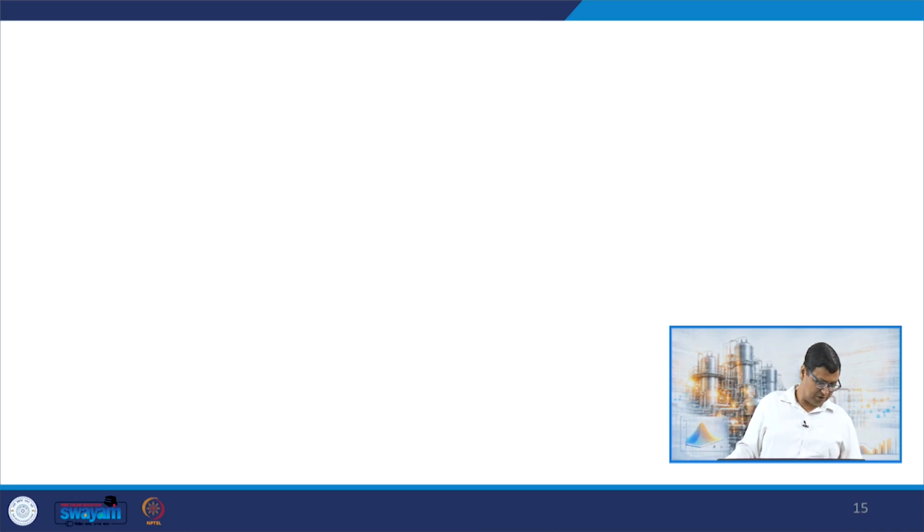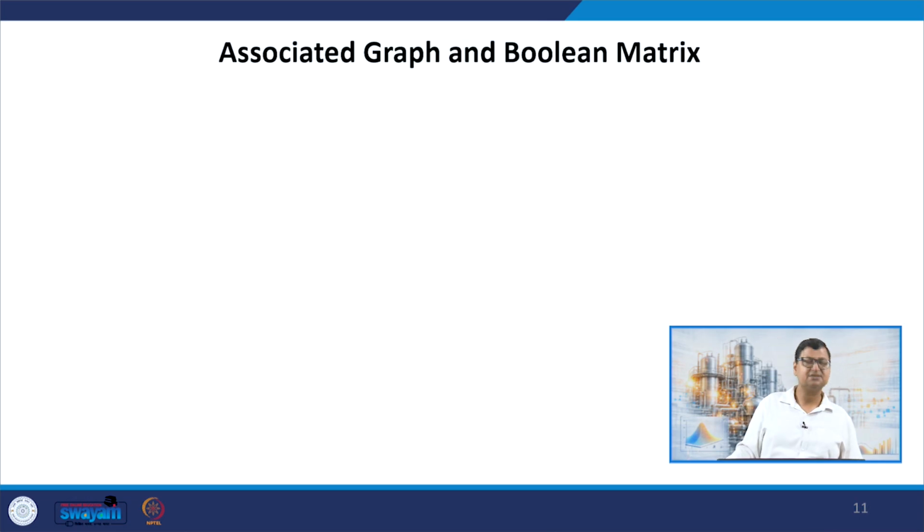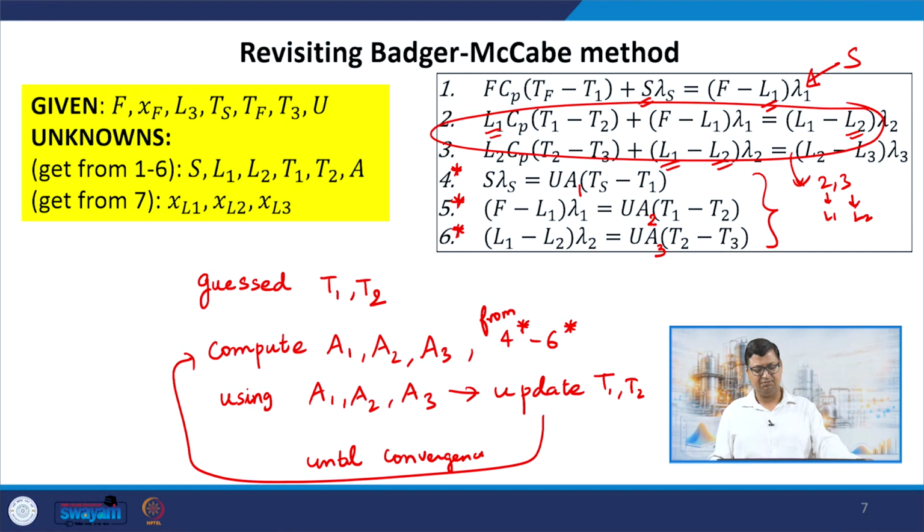Again, for this particular example, we only had a 6 by 6 matrix. So, the benefit from doing this iterative scheme may not be as high, since we could have done a Newton-Raphson for this, and as we have demonstrated, it works quite well. But as we extend this idea to a much bigger system, let's say a flow sheet containing thousands of units, if we can nicely identify the tear streams, that can reduce the complexity of the problem to a very large extent.